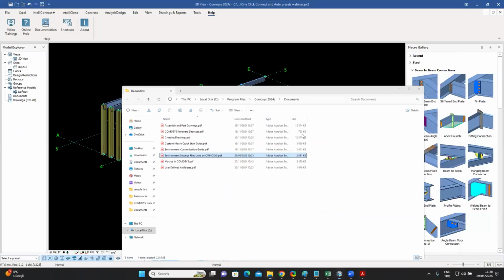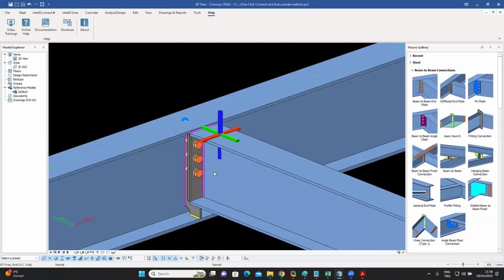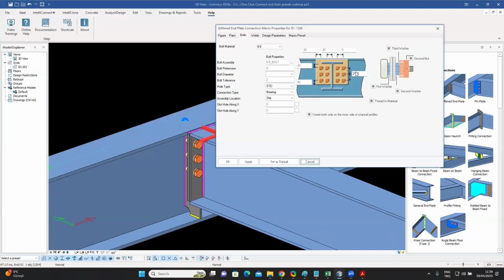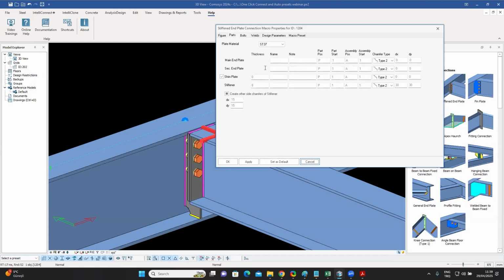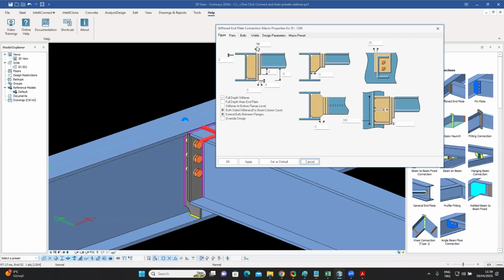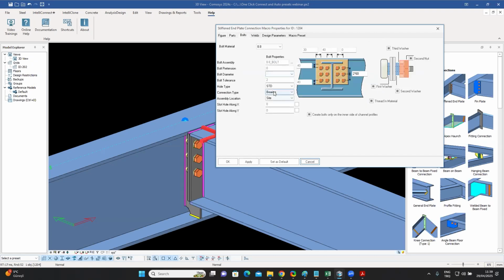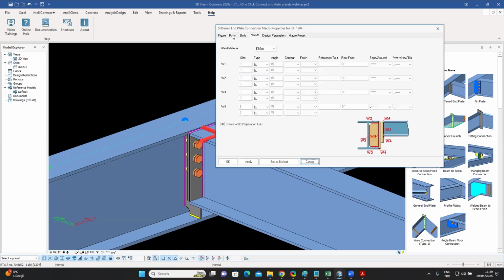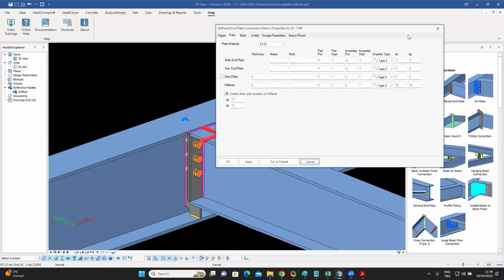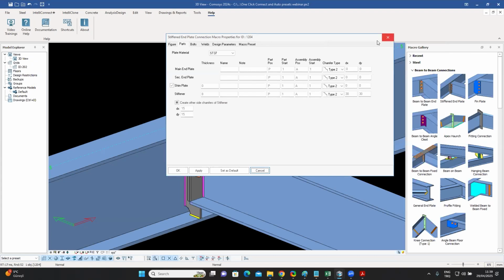The major thing which it will do for you is things like the interbolt distances. Now, normally, if you remember, I needed to enter these interbolt distances manually. Similarly, things like available plate thicknesses. So you can have some plate thickness in mind, but the plate thickness might not be available. So it covers the available plate thicknesses in the market. It covers things like interbolt distances, some parameters related to welds, etc. as well. So those things will come from project preferences.